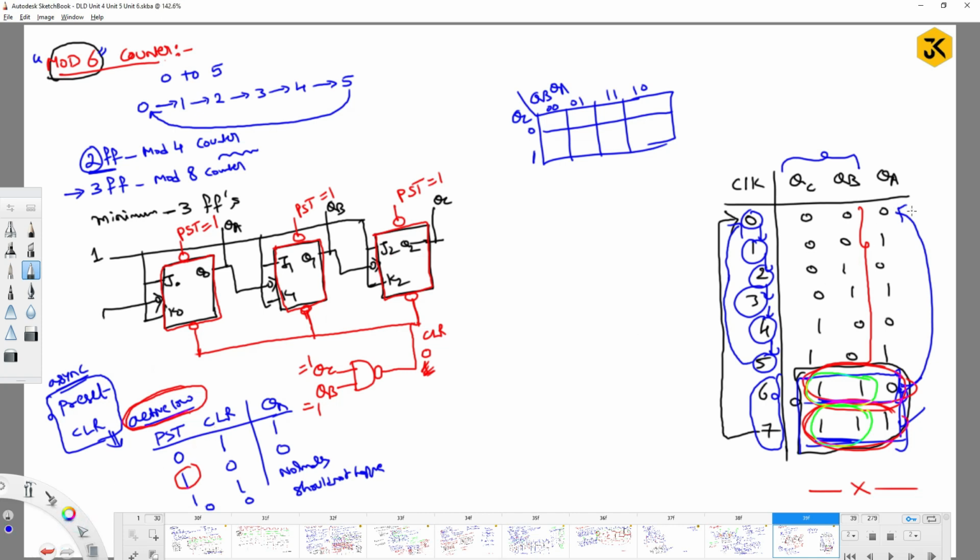As I am constructing the circuit for active low, all these values are basically 1, and for this value I have to make them 0. This is the value I require. So if I place them, 000 we are going to get 1, 0 0 1 1, 0 1 1 1, 0 1 0, 1 0 0 1 0 1. So up to here we need all the ones. And what about 1 1 0 and 1 1 1? Those are 0. And from this place onwards you can take the value as anything, right?